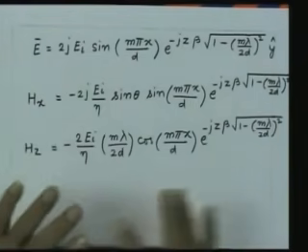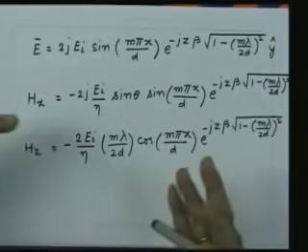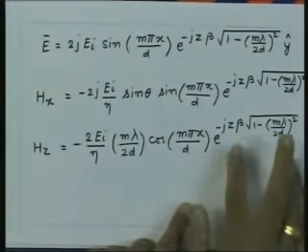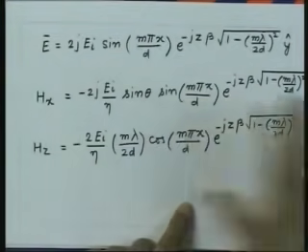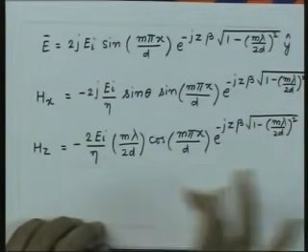So, when the net wave propagation takes place, this quantity beta does not have any meaning, because beta is the phase constant of a uniform plane wave which is bouncing back and forth between these 2 conducting planes. What phase constant essentially we are going to see for the net propagation will be the total quantity. So, we say that the phase constant for this mode, which is a superposition of 2 uniform plane waves, is this quantity. The mode is going to propagate with a phase constant which is this quantity.